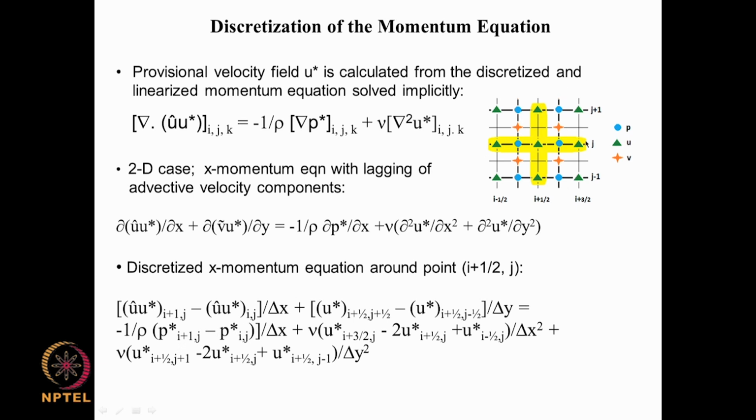So, these are the 4 neighboring points which are being added to this to give you u star, but the coefficients themselves that need to be evaluated are this u, we need to have this one u star evaluated at I plus half, and then u hat evaluated at I plus half, like that. So, if we are able to come up with prescriptions here, then we will be able to complete this discretization here.